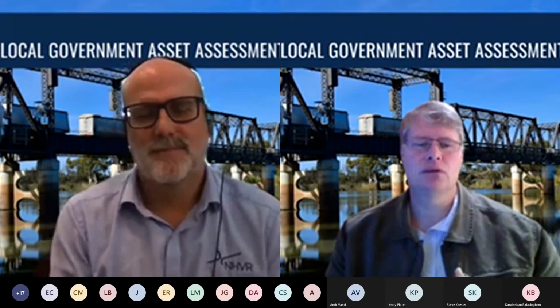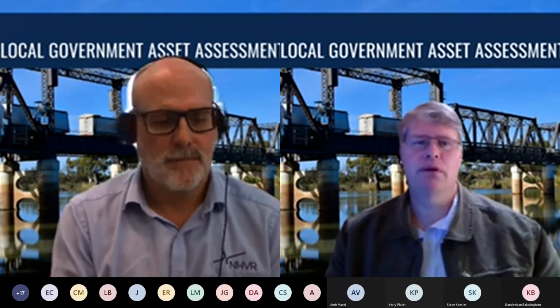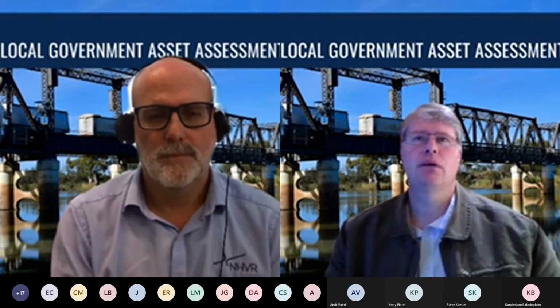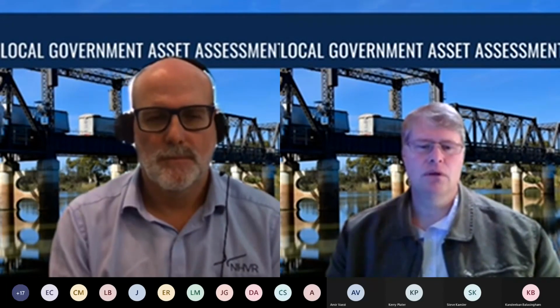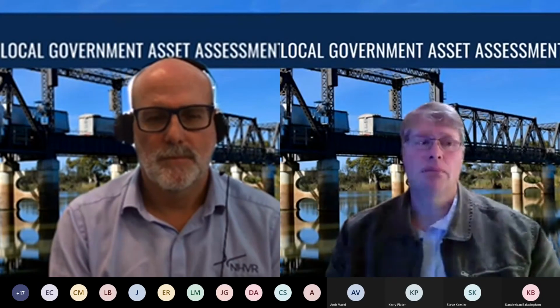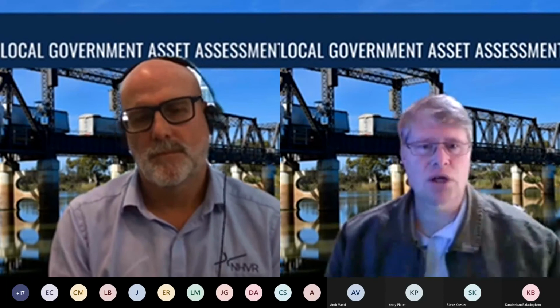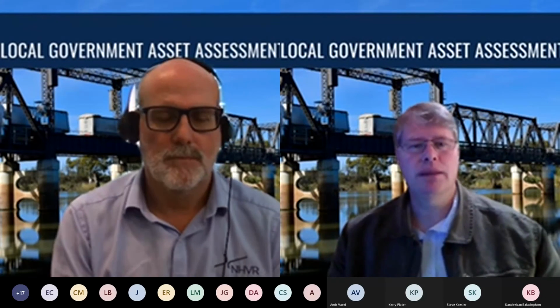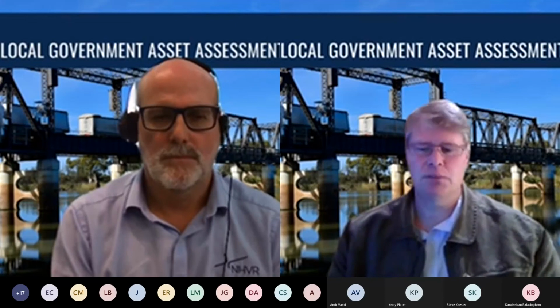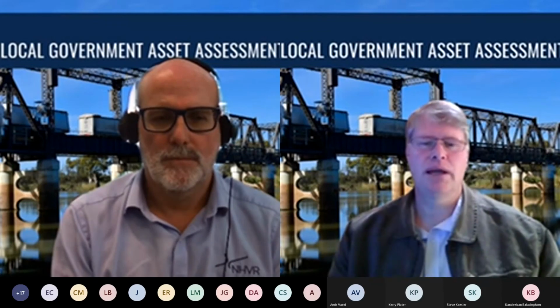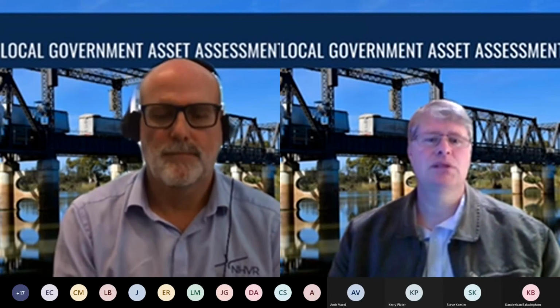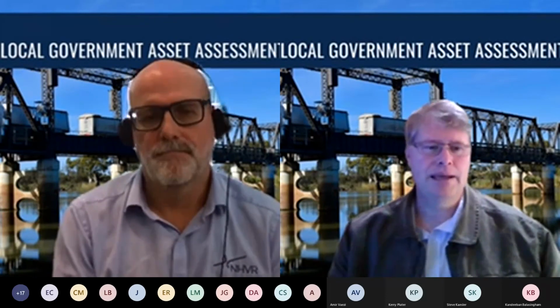When you are going out to procure a Tier 2 assessment, it's really important that you're very explicit around what you need done. In the documentation around this strategic local government program, we've said that you, as a supplier, can make an assessment of the substructure based on your experience. But we have said that they have to stand behind their results. So you could go by experience and inspection, and say the substructure will be strong enough and the risks are low. But what we've insisted on is that a supplier doesn't say the substructure hasn't been considered, because that's not useful to us. What we need to know is, can this bridge take this load? So they need to make some assessment on that.